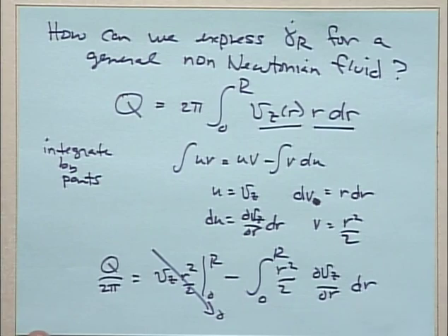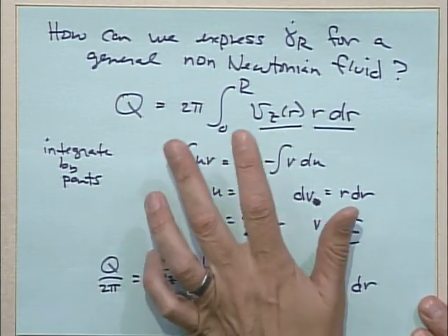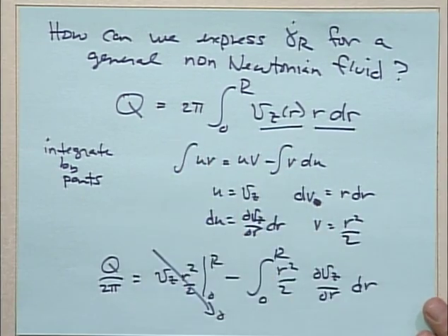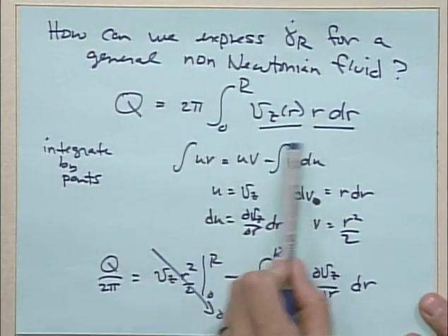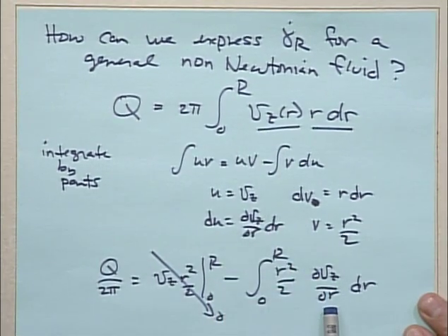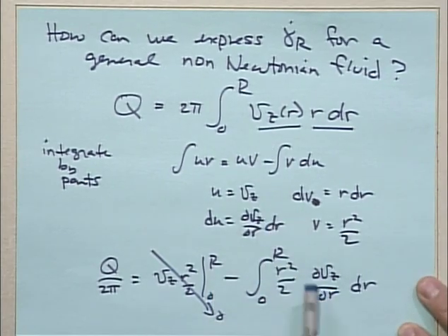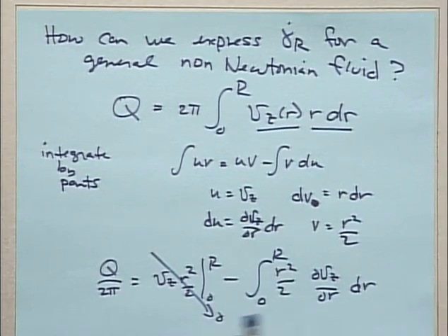We started with the flow rate as a function of the velocity field and followed the Weissenberg-Rabinowitsch derivation to get an expression. So looking back over the calculus that we did, we first did an integration by parts, which turned the velocity into shear rate. That was a way of taking our flow rate versus velocity expression and making the shear rate appear.